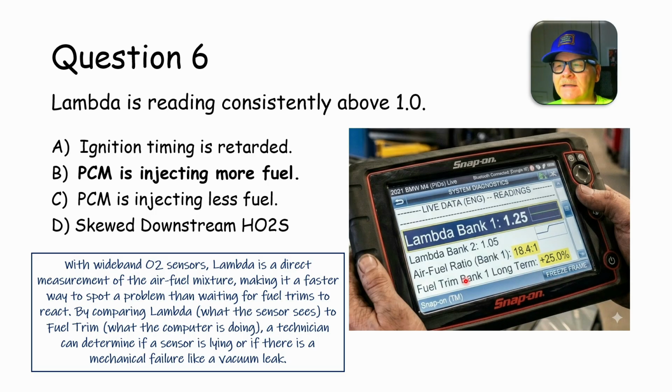But whenever you look at this, let's say you clear this, right? And you got this long fuel trim back at 0, and you're watching your long and your short fuel trim. And if you think you have it fixed, and let's say you found a leak or did make some repair, start it up and watch that short fuel trim. If it goes crazy and starts to go plus again, you're not done.